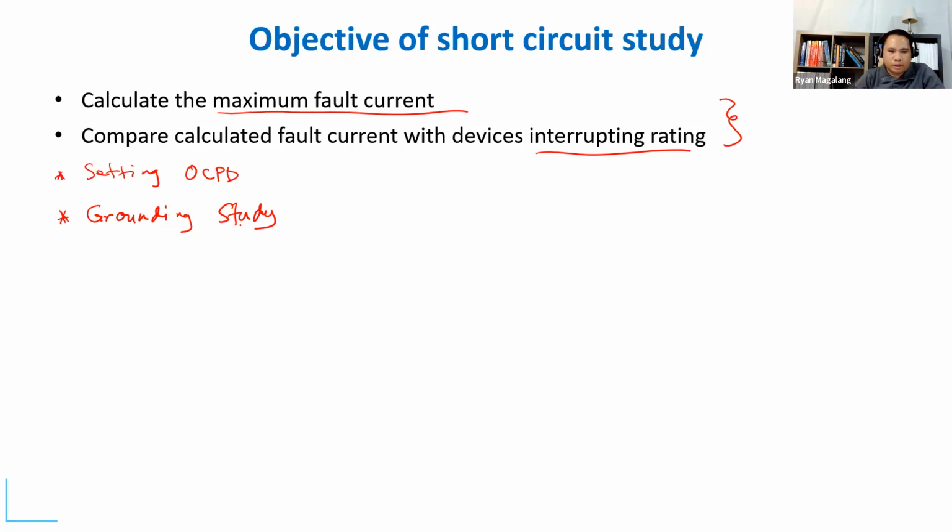The objective of that study is to determine how much current and voltage is expected to flow should a person touch some of the metallic objects in the substation. So short circuit analysis is conducted in order to do that.